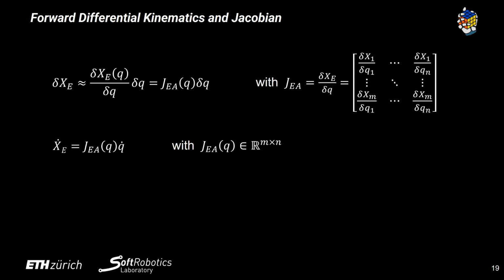So knowing the forward kinematics, can we also map the joint angular speed to the end effector speed? The answer is yes. In forward kinematics, the end effector is a function of joint angles. To get the speed, one just needs to differentiate the forward kinematics one time. Then we would get an equation with the end effector speed as a function of the joints' angular speeds.